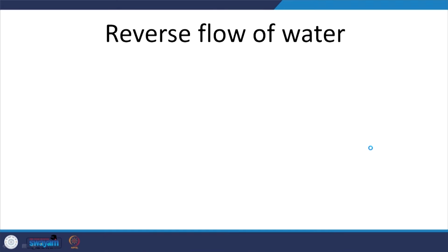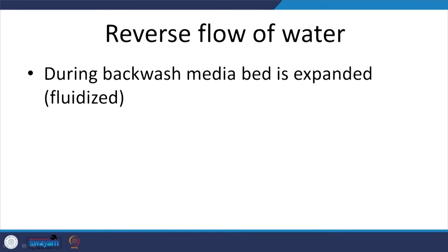Let us move on. So, reverse flow of water. We just established the need for backwashing. Usually water flows through the media this way, right, but we need to backwash it from time to time to decrease the head loss and also prevent this negative pressure from being developed within the depth of the relevant filter. So, what do we do? We are going to have to backwash or fluidize the bed.